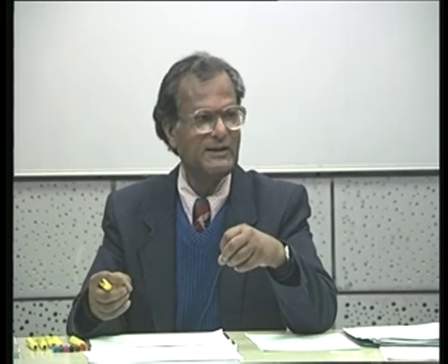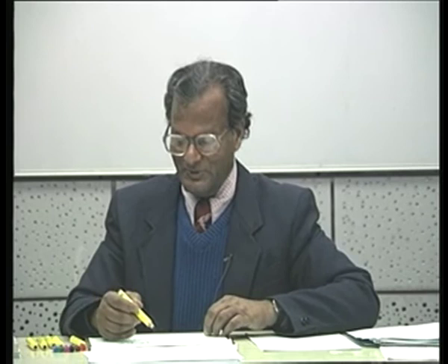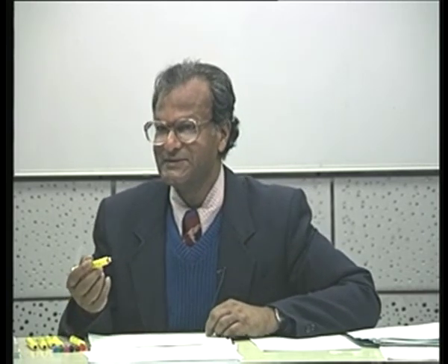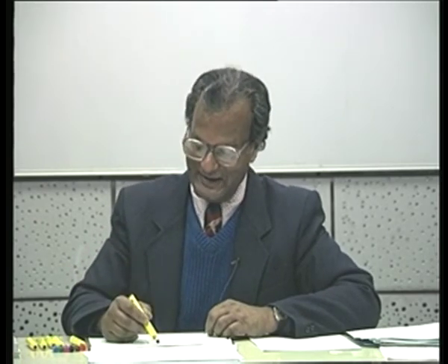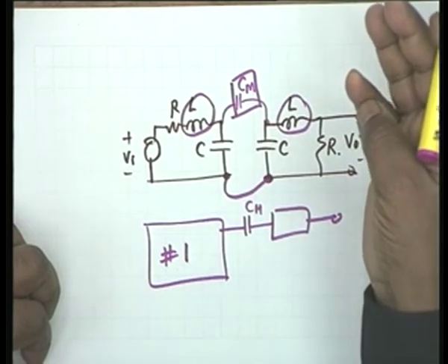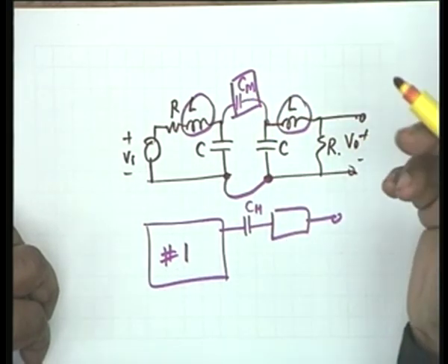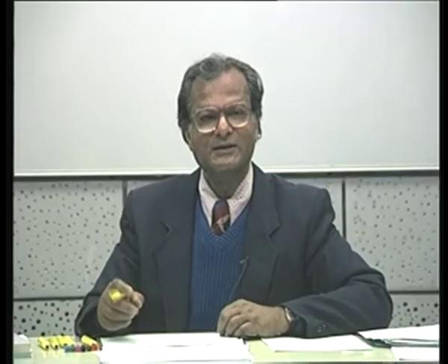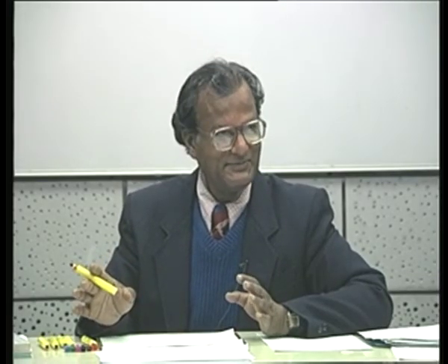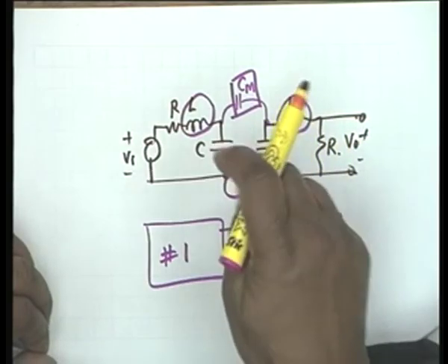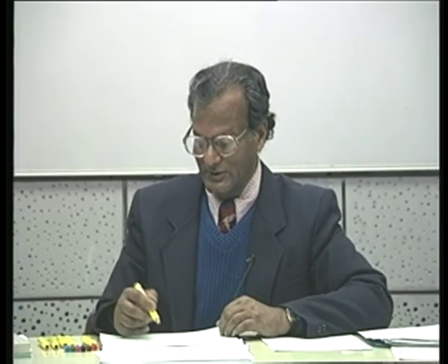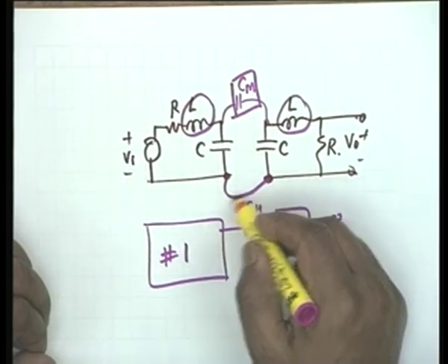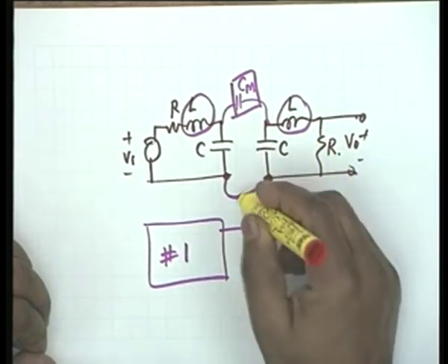This is called electrostatic coupling. Is it possible to replace the capacitor by a resistance? Of course it is possible. Anything connected here, it could be resistance, inductance, capacitance, anything which is non-infinity in impedance. Is that clear? A finite impedance connected here is adequate for coupling two circuits, provided they have a common reference. There must be a common reference.